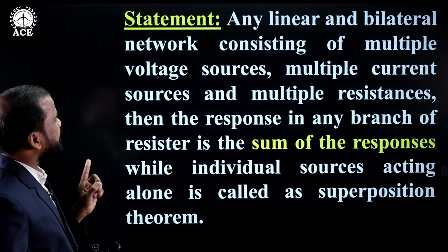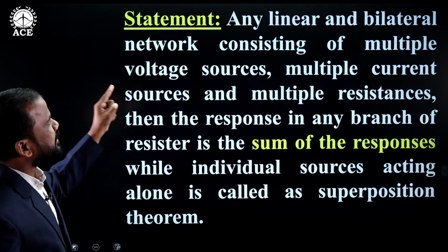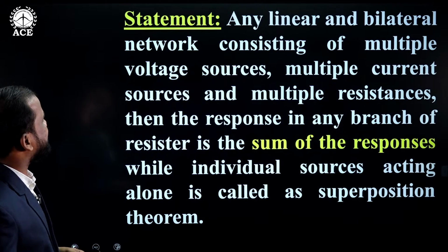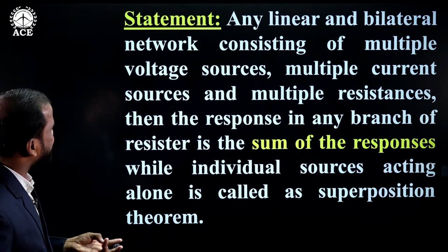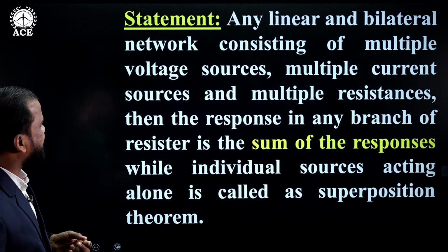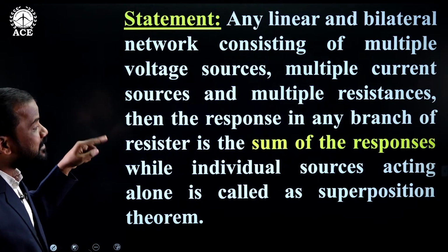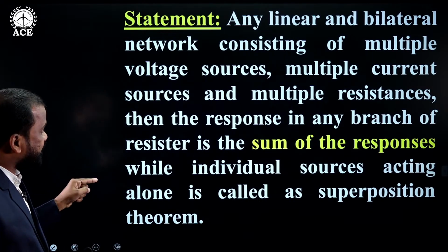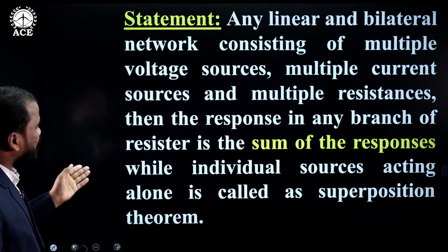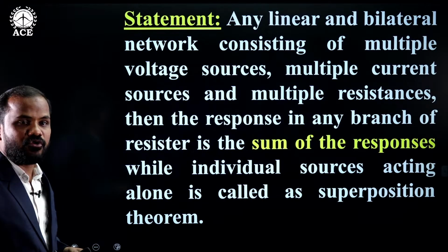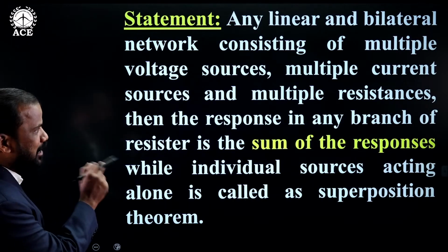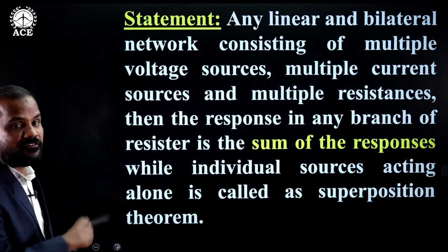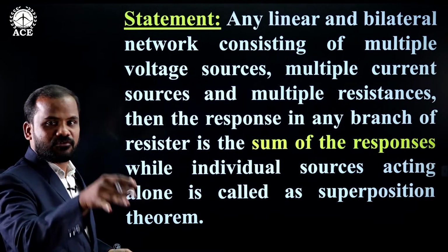Once again I am repeating the statement. Any linear and bilateral network consisting of multiple voltage sources, multiple current sources and multiple resistances, then the response in any branch of a resistor is the sum of the responses while individual sources are acting alone, is called the superposition theorem.